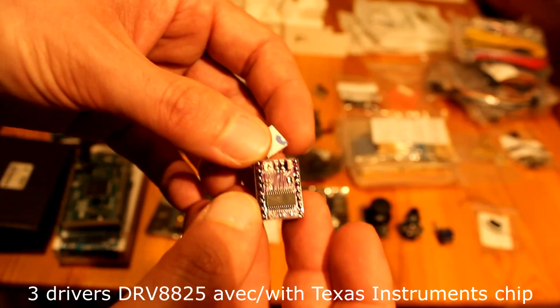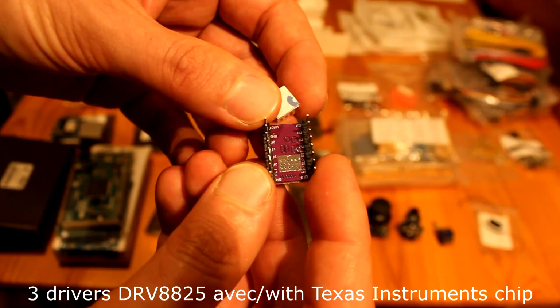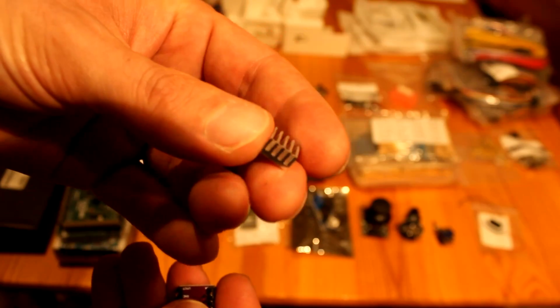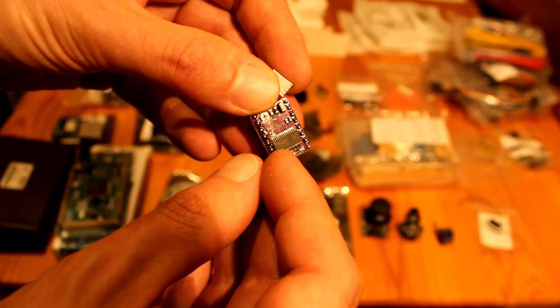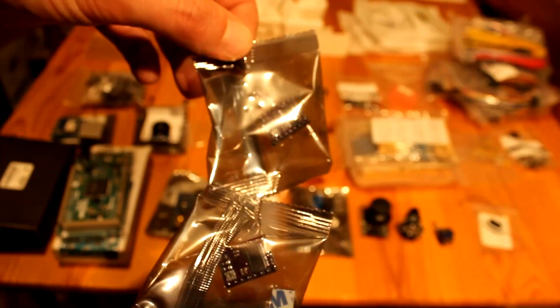Now let's take a look at the drivers. This is Pololu DRV8825. It comes with a little aluminum heatsink. I replaced it with a bigger heatsink for better thermal dissipation. If you purchase it on AliExpress, make sure you have the TI logo on the main chip. There are 3 drivers for the 2 motors and the microfocuser.